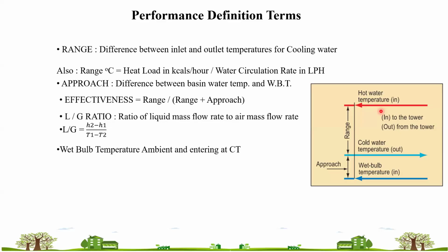Your cooling water is very critical in this phenomenon. If you are providing a higher inlet temperature, you will not be able to do better heat rejection, so the compressor has to do more work. If the compressor is doing more work, your condensing temperature goes up and condensing pressure goes up, and it will consume more power. So the entire chiller performance goes down.